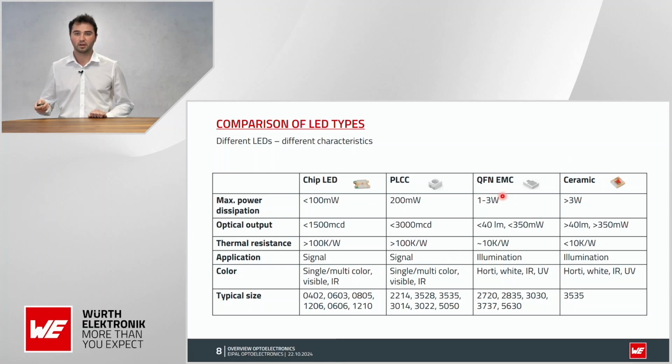If you want to go to a higher power, so when do you want to use higher power LEDs? You want to use them when you try to illuminate something. So not when you just want to see the LED, but if you want to make the LED shine light on something so you can see this something. So for all illumination purposes, you would use the higher power LEDs.